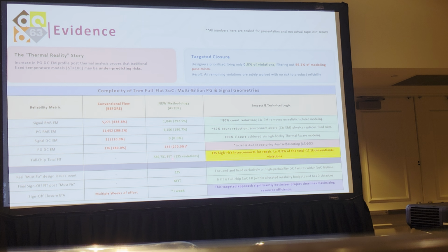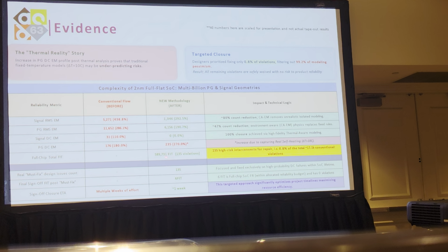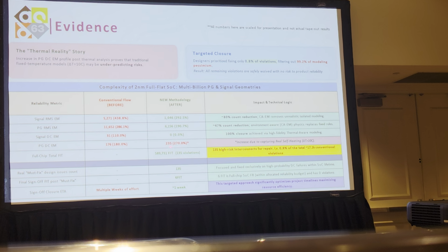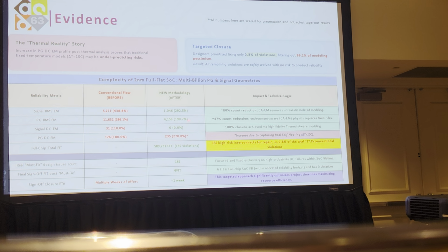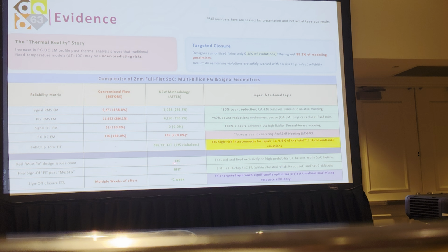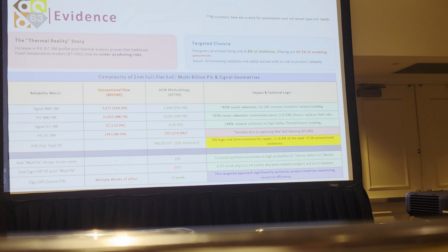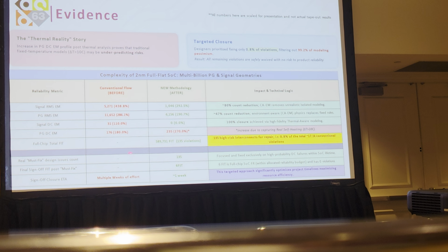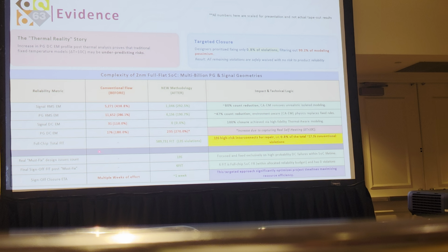These are the violations which have FIT greater than 1. All these will have different FIT values for each of these 135 segments. On adding all those, it accounts to 0.5 million. So among the 17K, we need to fix only 135 violations which are really risky in the long term, for example, say 5 years or 7 years. After fixing these 135 violations, on adding all the segments' FIT, it was under 6, which is within our FIT budget. And fixing these 135 only took 1 week of effort instead of consuming all these weeks of human effort and resources.